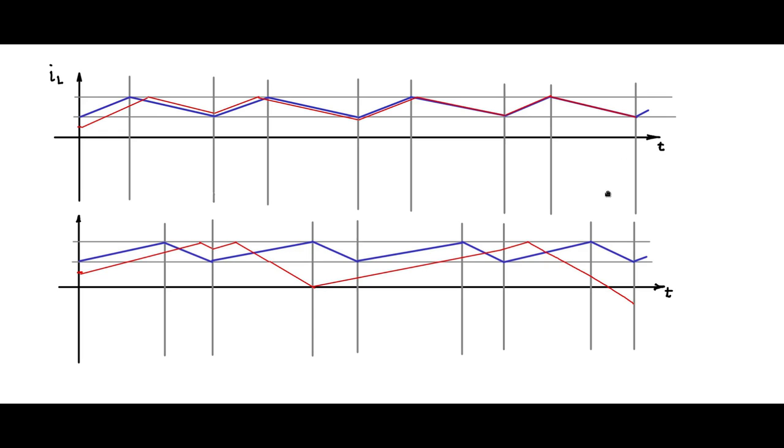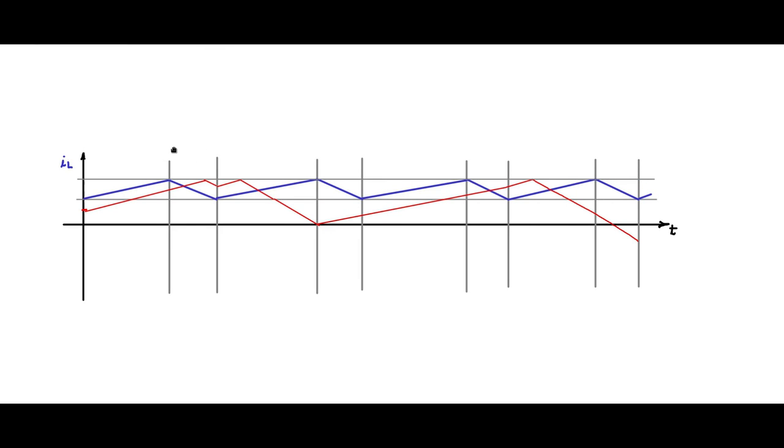How do we solve this problem? Let us seek a solution and try to find out how to implement that. Let me consider the problem case waveform. Here the duty cycle is greater than 0.5, and we see that if we give a disturbance, the disturbance keeps growing and leads to an unstable inductor current waveform.